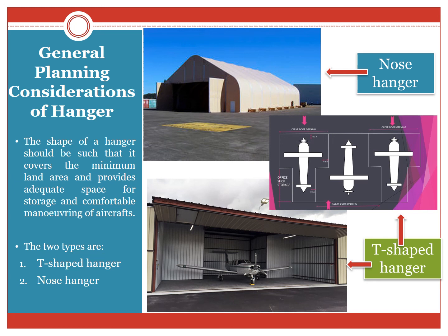Now, what are the T-shaped hangars used for? These are provided for small-sized aircraft. In this design, the storage space is so arranged that the pilot can maneuver the aircraft in and out of the hangar without any assistance. The area should be such that a minimum clearance of 30 centimeters is available on all sides of the aircraft. Now look at this figure. The figure down below shows you the T-shaped hangars.